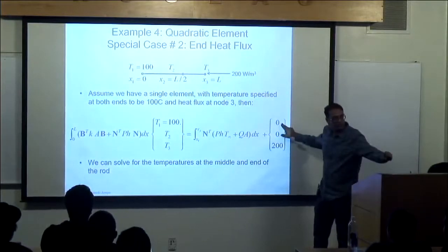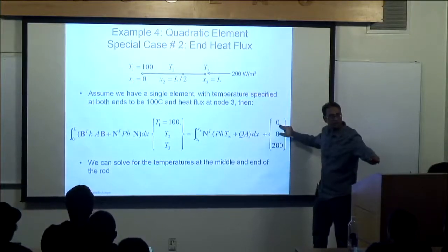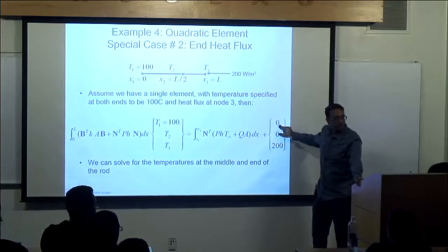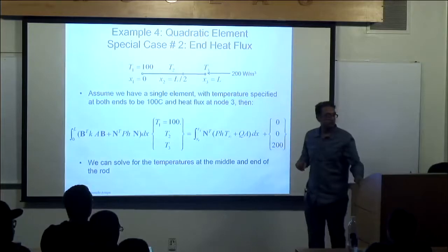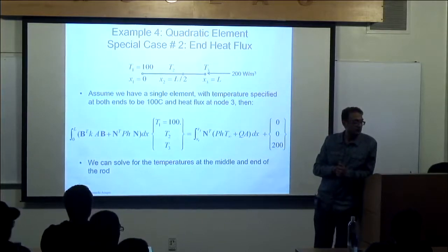Can you make a note so I can put some Q here so they know that that's basically a reaction force? Yeah, actually, I was going to ask you about that. When we are solving a 1D problem in elasticity, and we are interested in the internal reaction forces, after we solve the global problem, we get back to each element and we can find each reaction force per element.